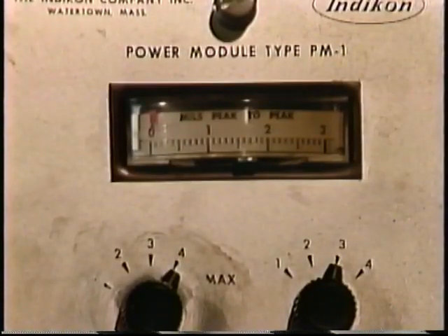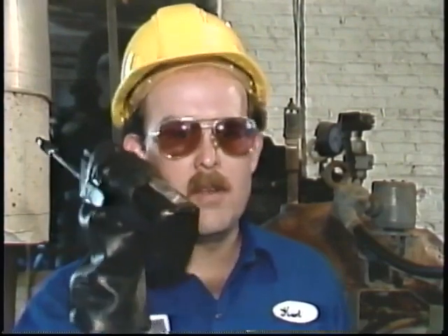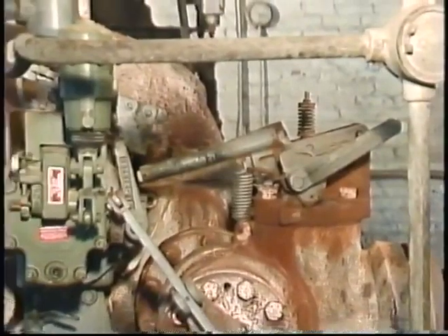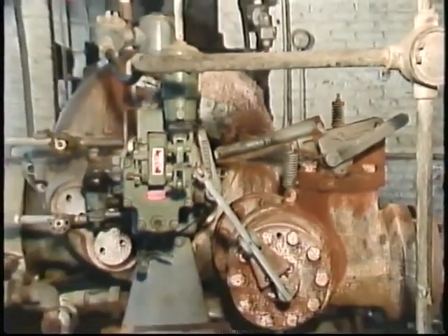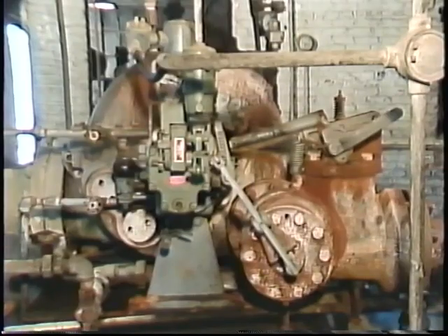Also, some facilities have special devices for vibration monitoring and detection. In any case, let your supervisor know if you find that the turbine or the driven equipment is vibrating severely. The turbine may have to be shut down to prevent damage. Then the problem that's causing the vibration will have to be identified and corrected.